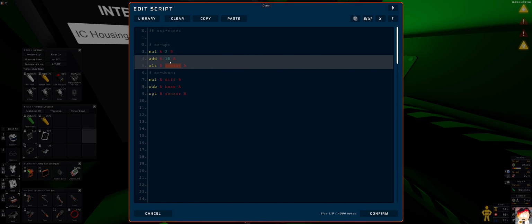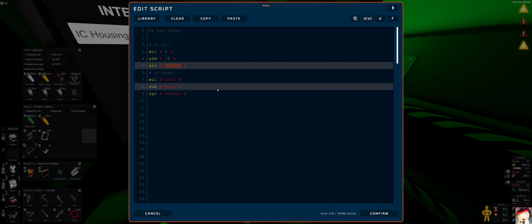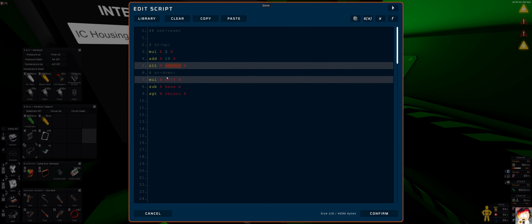11, still 0. Drops 10 and below, it triggers that the sensor is 1, but then it's now rising, and it's 11 still is 1, 12, oh, I need to turn off, and that's it, right? So it doesn't just flip this on off state and so on. Obviously, if it's outside these ranges, the range below 10 means that I need to turn on, but range above 12 in this example will be I need to be turned off, right?